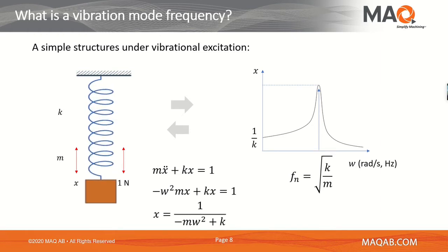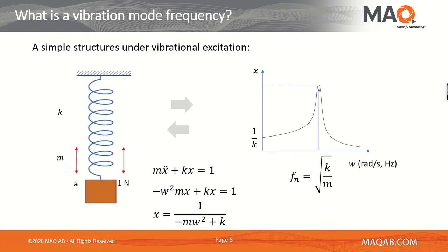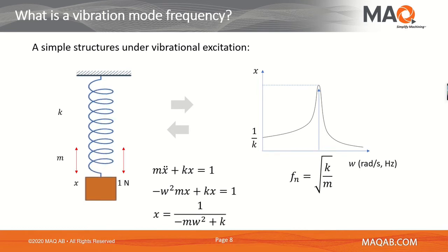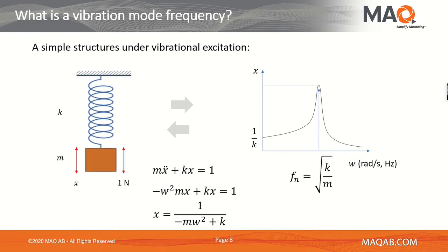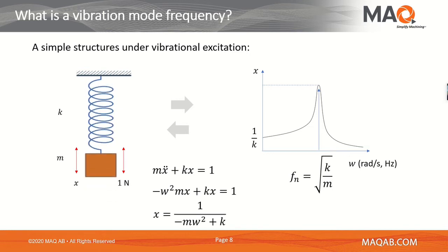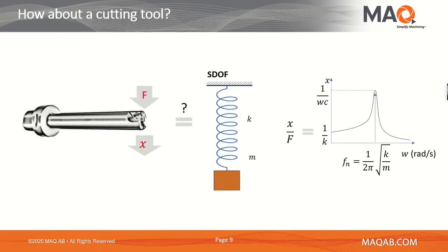And we start to realize, oh, the system by itself has a natural frequency where it gets easily to be excited. There are, of course, equations developed by mechanists, and if you have time and you want to know more, you can always look into the details. But today, what I want to tell is that every mechanical system has a natural frequency or more natural frequencies where it gets easily to be excited with a very small force. So a very small force can create a big displacement or big vibration in a system.